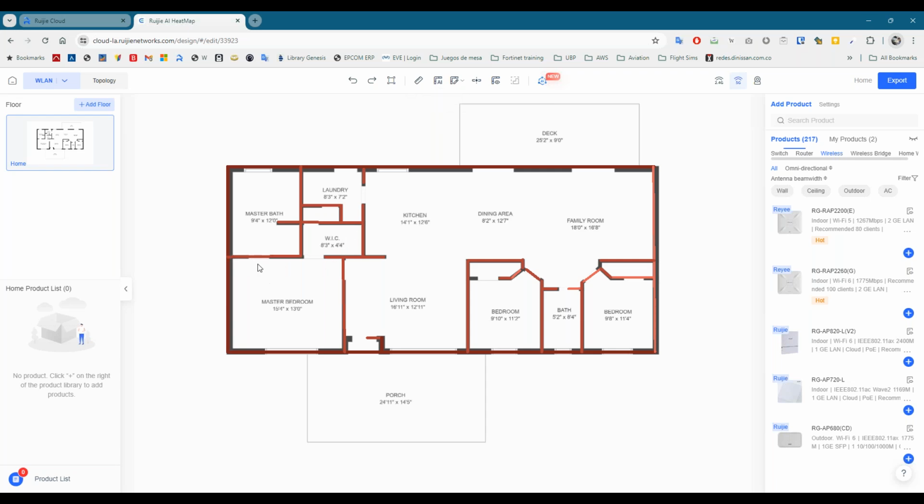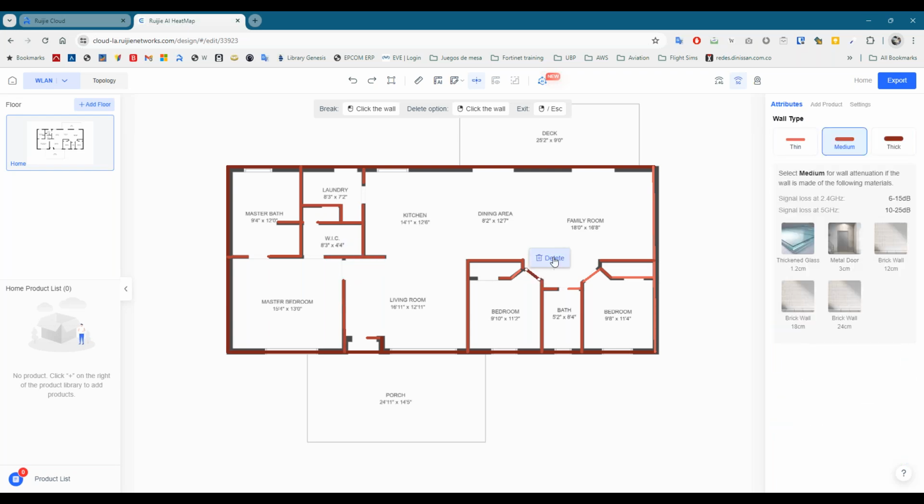So based on this, it will calculate the entire area and the walls. Since we have here some open spaces and doors, we have the truncate wall tool where, with a couple of clicks, you can delete and rearrange doors and open spaces as well. So let's say that this is a door and we need to click those spaces just to remove them.